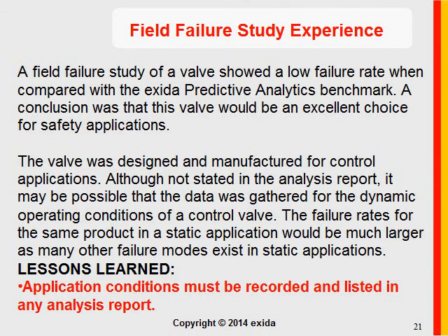Another example, and I think this is our last example here. A field failure study of a valve showed a low failure rate when compared to the exida predictive analytics benchmark. That's when we evaluate a product as part of our 61508 certification work, we predict a failure rate based on the design of the product. In this case, the field failure study showed an exceptionally low failure rate, and one would say, hey, this device is behaving a whole lot better than predicted.